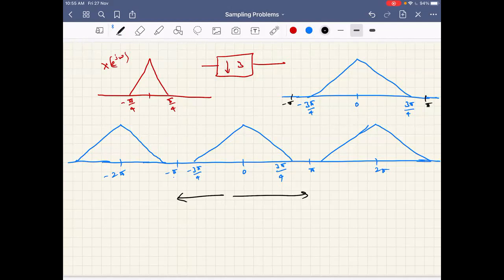The non-zero frequencies, do they go over minus pi to pi? No, sir. So, no aliasing. Just noticing one spectrum after expansion is good enough to judge whether there is aliasing or not.